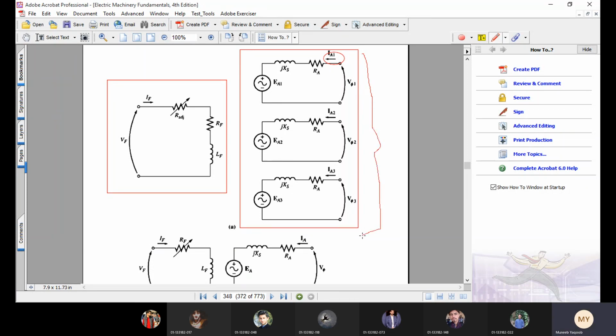with three-phase power supply. They have not written it here, but I am telling you that on the right hand side, what we have is basically a three-phase supply. Like in a single-phase motor, we provide the motor with a single-phase supply. So a three-phase synchronous motor has a three-phase supply towards the right-hand side. Now, when we connect these three phases to the three terminals of the stator, obviously, current will flow from the supply side towards the motor side.